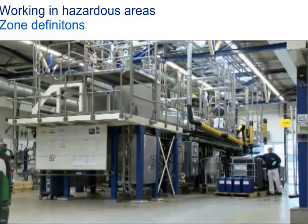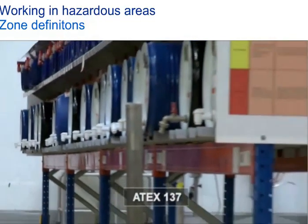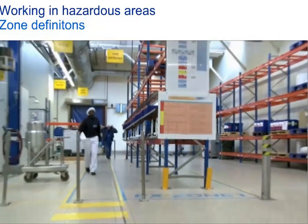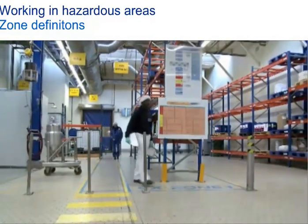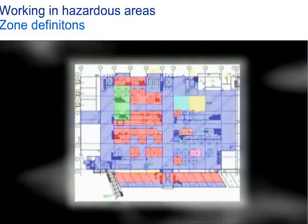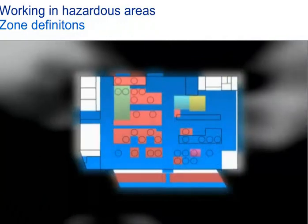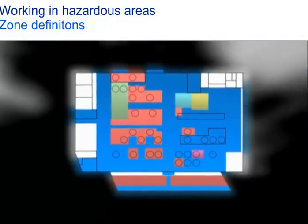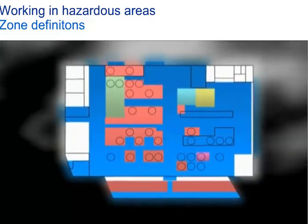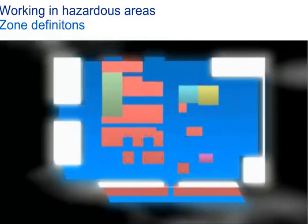In some cases, it is not possible to prevent the occurrence of potentially hazardous atmospheres at the workplace. In accordance with European Directive ATEX 137, these explosive areas, which may be present in rooms or even in items of apparatus, must be subdivided into different zones, and appropriate measures must be taken to prevent the presence of sources of ignition depending on the danger posed by each of these. This zoning is performed as a function of the frequency of occurrence and duration of such hazardous atmospheres, and is defined separately for dust and gas explosion hazards.